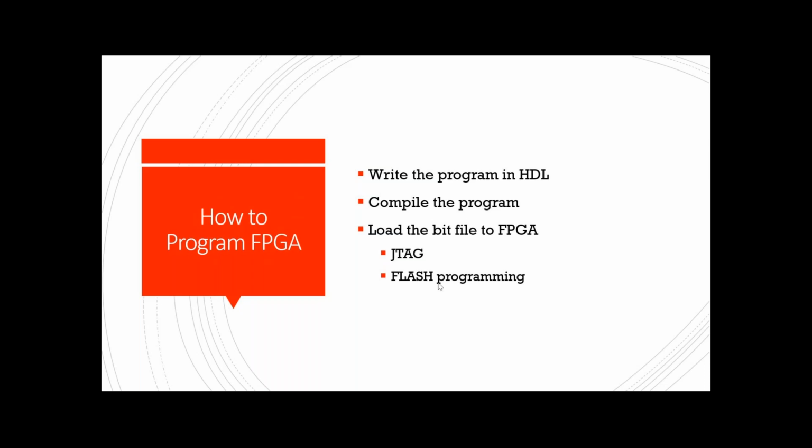Whatever I said, I'll be programming into the FPGA memory. That is a volatile thing. As soon as the power goes off, the FPGA will be blank, it does not have anything. SRAM is volatile, so as soon as power goes off, everything is erased. Each time we have to keep loading the values. JTAG-based programming is only during debug: through tools, we program the bit stream via JTAG, and the FPGA acts like the circuitry you want.